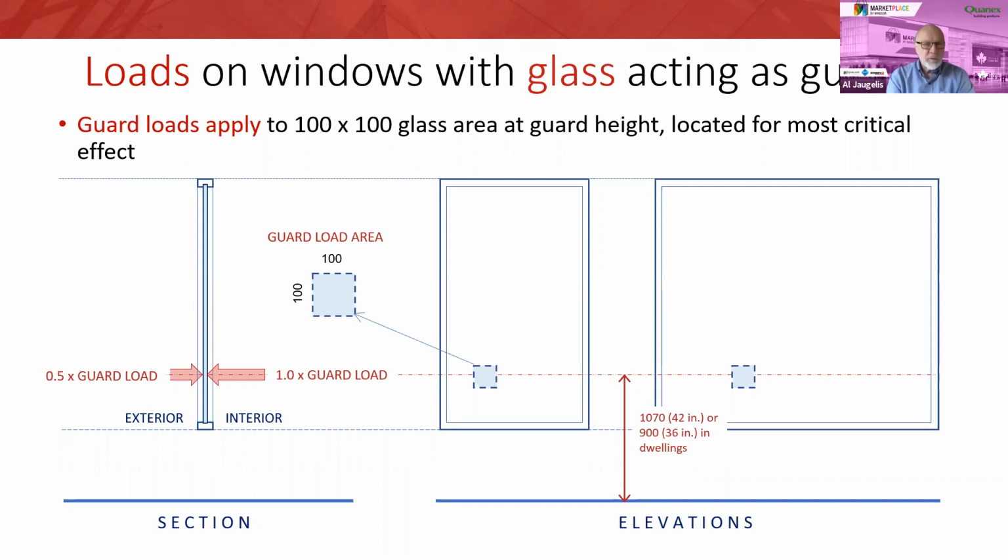Well, if this window was only 2 feet wide, is it possible it might work with annealed glass? Well, I started using an online available free software recently and playing around in there. I'm thinking that the answer is no. I have not done an exhaustive comparison of all sizes, but it doesn't seem to reduce the stresses greatly that the light size is smaller. I see. Okay, that's interesting.